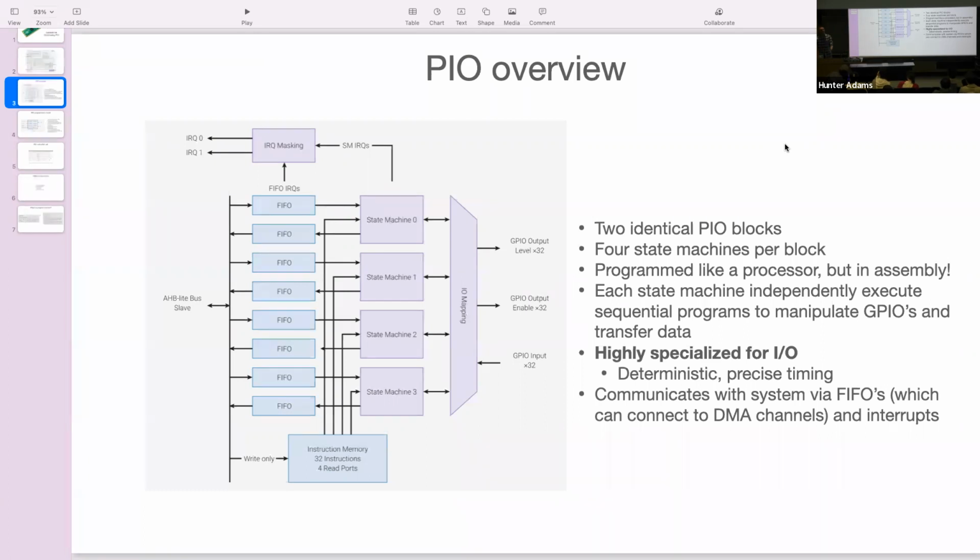Now you can introduce delays, right? Like you can have a program wait to run until it's signaled by some process that's harder to predict, something that's running on the ARM. But you can have an independent PIO program that is completely deterministic. You know exactly what it's going to be doing on every single cycle. Programs like that, highly deterministic programs like that, are, for me at least, something I typically only associate with things like FPGAs, right?